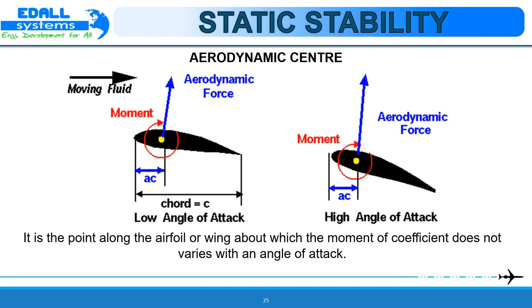is applied. It has been found both experimentally and theoretically that if the aerodynamic force is applied at the location of 1/4 chord back from the leading edge on most low-speed airfoils, the magnitude of the aerodynamic moment remains nearly constant with angle of attack. Using the aerodynamic center as a location where the aerodynamic force is applied eliminates the problem of the movement of the center of pressure with angle of attack in aerodynamic analysis. For supersonic airfoils, the aerodynamic center is nearer the half-chord location.